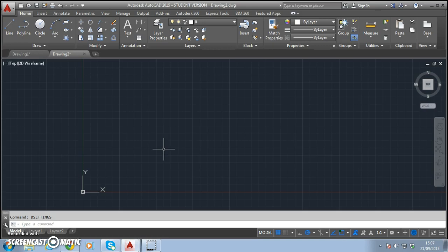So take an example. If you have two coordinates, you draw a line from one coordinate to another coordinate. If you've got an angle and a distance, you draw a line along the angle and the distance, but you really need a start point. So you need a start point, an angle and a distance, and that will draw a line for you as well. The other way you can go about doing it is if you have just the angle and the distance, and you just decide upon your own start point. You can do it that way as well. So there's a number of ways of doing this, and these are referred to as the absolute coordinate method, the relative coordinate method, and then the polar coordinate method. And we'll look at all three here now.